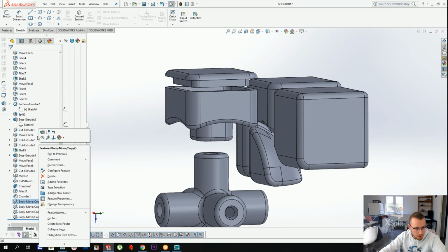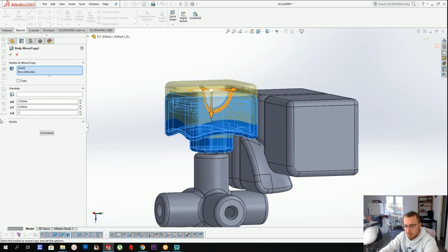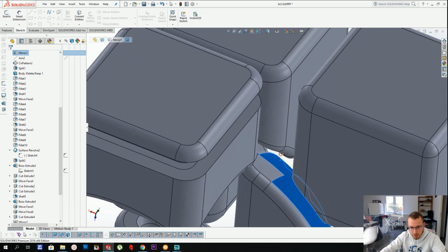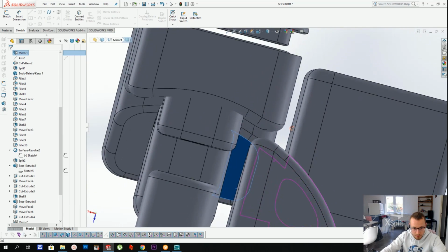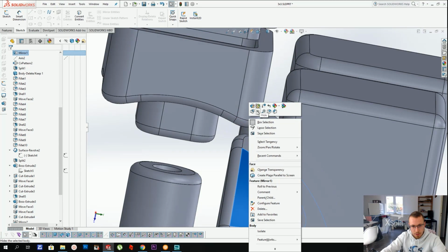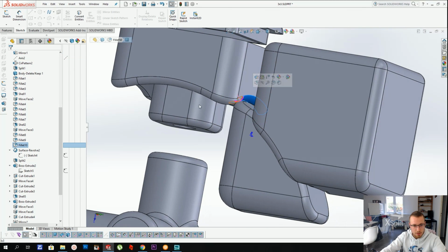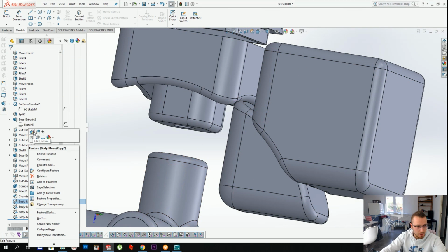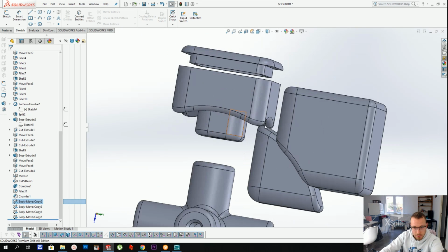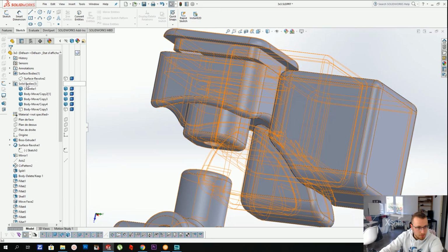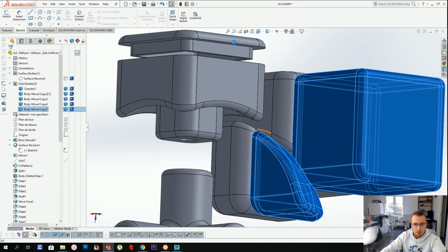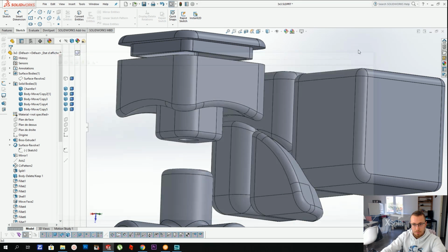I'm almost there. Just need to tweak a little bit at the positions, and here, as you can see, the corner isn't touching the edge. It's not touching here either. Here, the edge is touching the center, which means we need to move the center back a little bit more. Let's say 5 millimeters. All right. So here, the edge isn't touching the center. The corner isn't touching the edge, and the corner is definitely not touching the center. So we're good. The parts don't touch.